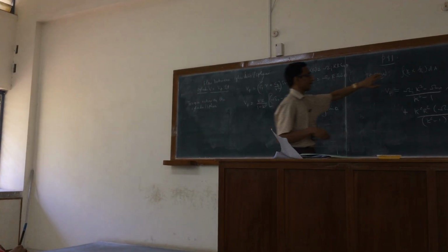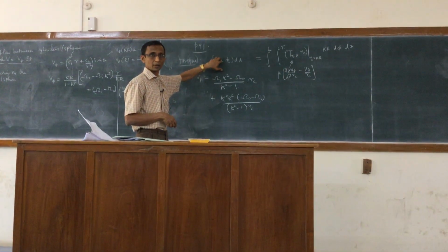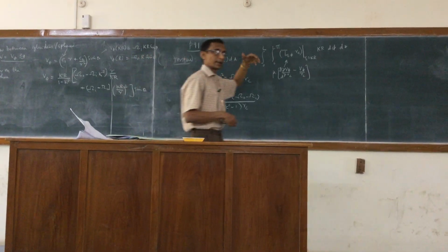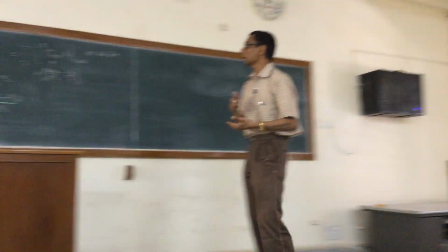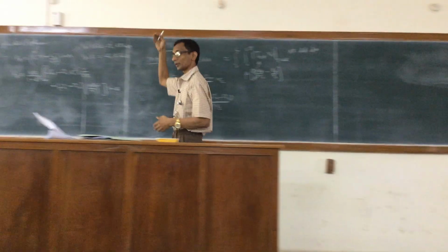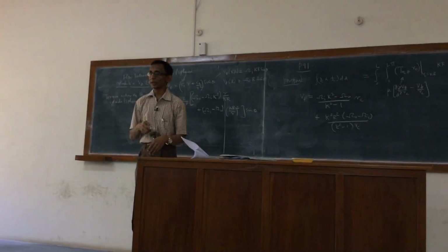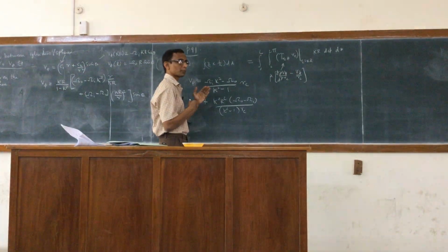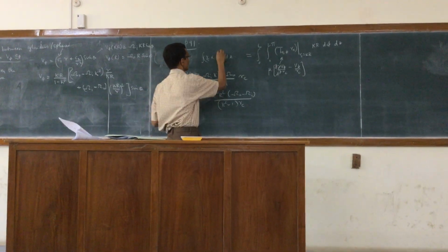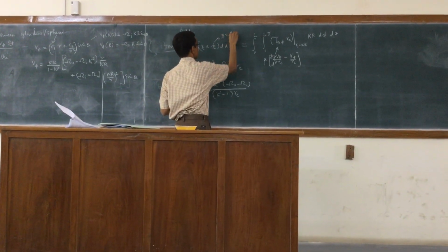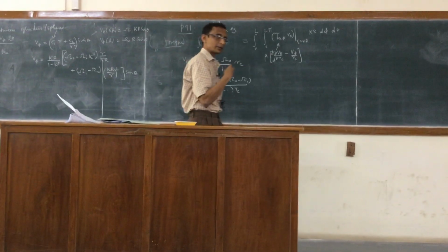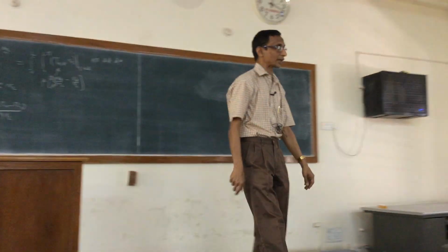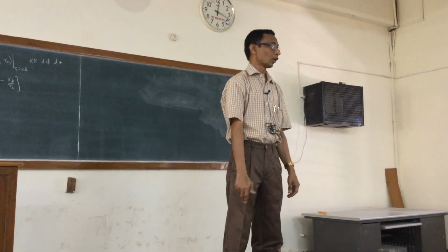So first you have to express x in terms of cylindrical coordinates. T has to be calculated or expressed in terms of the stress tensor, which is n dot tau. Now what would be n here? We are calculating on the surface of the cylinder. N would be ERC. So the sign is important for the inner cylinder, I think n will be coming out of the inner cylinder. So n would give you ERC, and I have to calculate n dot with tau. And then I calculate the cross product of x with that. The x is also expressed in terms of the cylindrical coordinates.